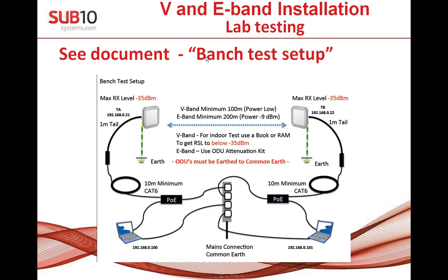This is from a document which is called bench test setup. There are key points which you have to follow to be sure that your setup will really work. First one, if you are testing in the lab, our recommendation is to use one source of electricity to avoid mistakes or some damages or issues that you are connected to different lines, because in some buildings you can see big difference between line 1, 2 or line 1, line 3, and this is good to use just one power outlet.